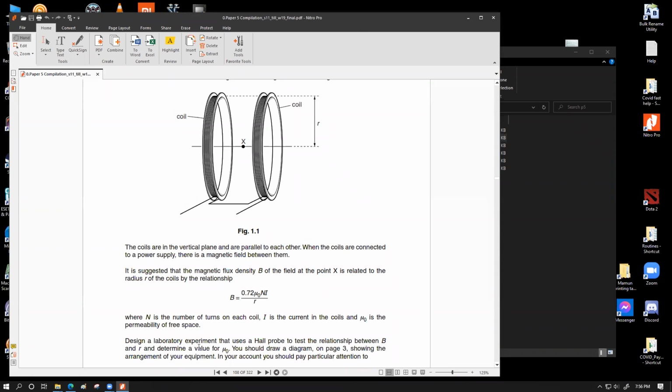A couple of things that can also be mentioned: while we are winding the wires, while we are making the coils, we can be careful not to make the wires overlap, or they should be placed side by side, parallel. It's not very imperative, but that makes a much better winding procedure, because that's how the figure proposes it should be done.